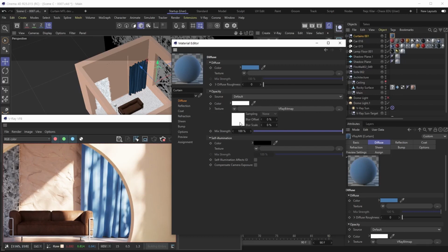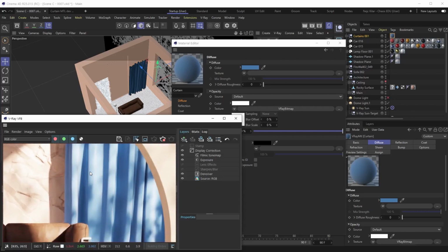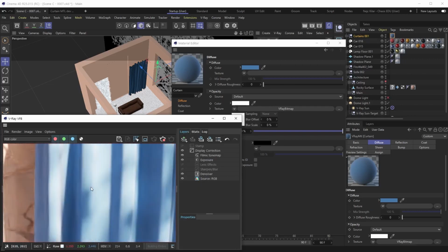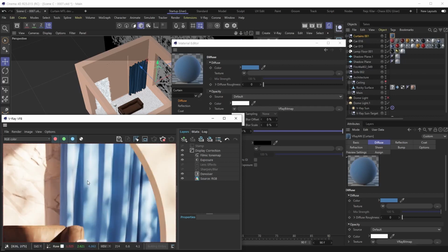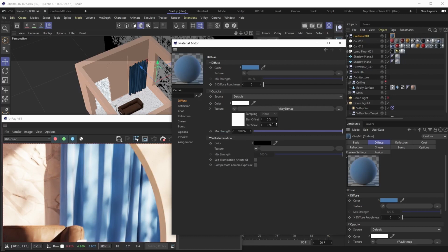But one effect that you could potentially do without is that see-through opacity effect that we've set up. It is a super realistic effect, but if you want to optimize your scenes, and if you're not going to look at these assets up close, because as you can see from where we're standing right now, we can't see through those strands anyway, we don't really need to have the renderer calculate the opacity on this material now, do we? If we go up close, we're probably going to need it for that extra realism.